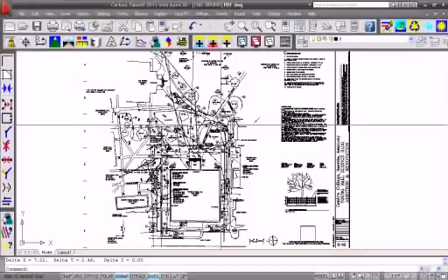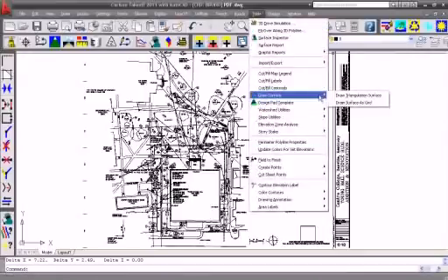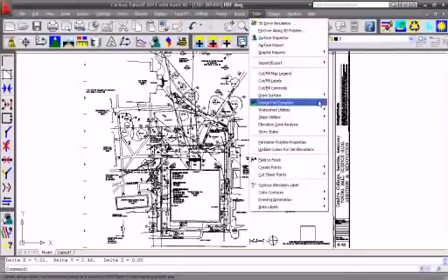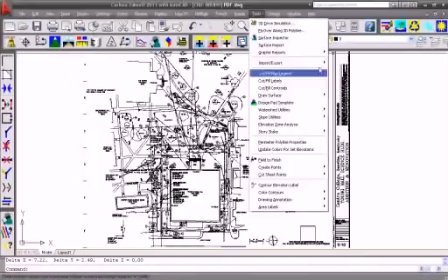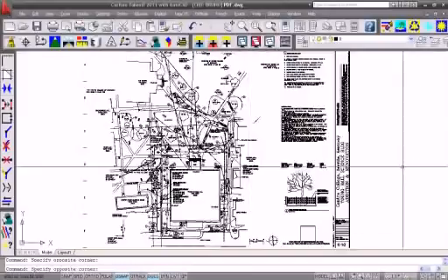So those are some of the new tools that we've created for working with PDFs: the ability to recognize the layers, the different colors in the drawing and put those out to layers, the ability to process text and dash polylines into continuous lines, and to scale the PDF in a simpler fashion.